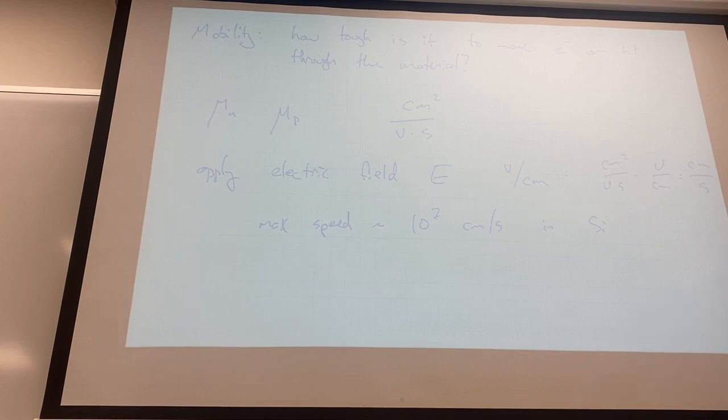This is the third of many times we'll encounter the word saturation in this class. This is velocity saturation, when everything's hitting the maximum speed. All right, we talked about there's a saturation state in BJTs. There will be a saturation region of operation for MOSFETs. There's velocity saturation. There's a lot of saturations flying around. None of them are the same thing. They all use the same word. It can be pretty bewildering.